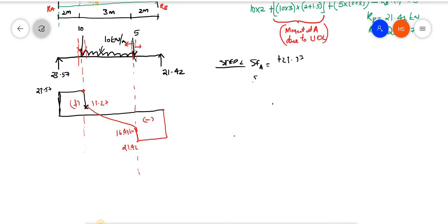First of all, we are finding the shear forces. Shear force at A we found. Now shear force at C. This is our point C, and I am taking the left, that is this line. What are the forces to the left? Only 23.27. Now I am considering the right also. Why two values? Because there is a force acting there, so I have to take left and right.